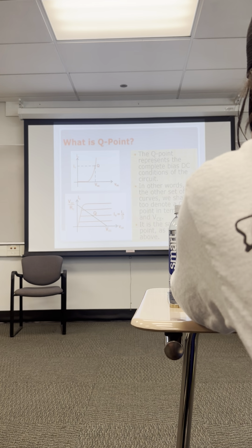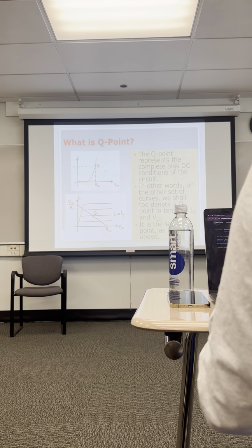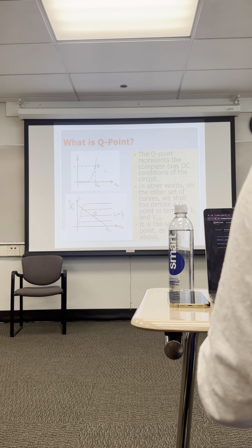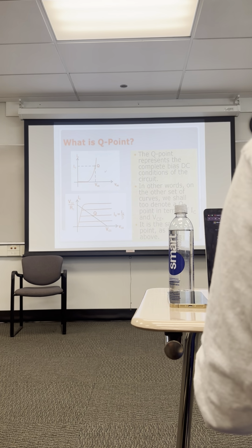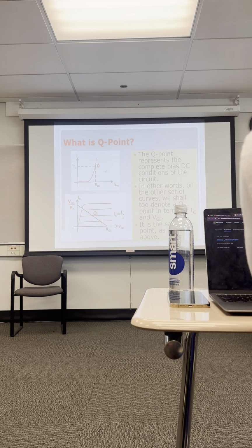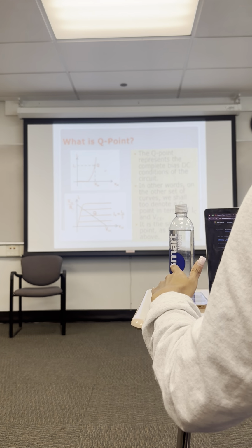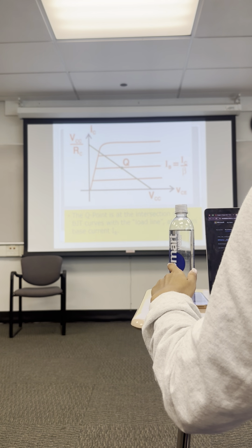So this basically is combining these two curves. This is the PN junction on the NPN transistor. And a normal design would probably select a Q point somewhere in the middle of these collector curves. And then I sub B is I sub C over beta. And then we would set up a collector voltage here, and then we'll have an I sub C at this point. And we've gone over problems where we set the collector current, and then we set the collector-emitter voltage, and that's called the Q point of the circuit.